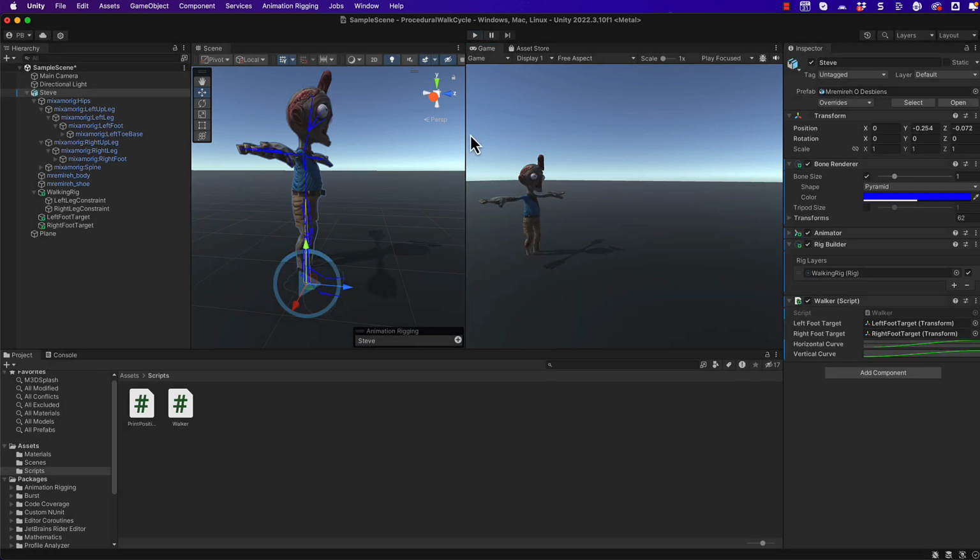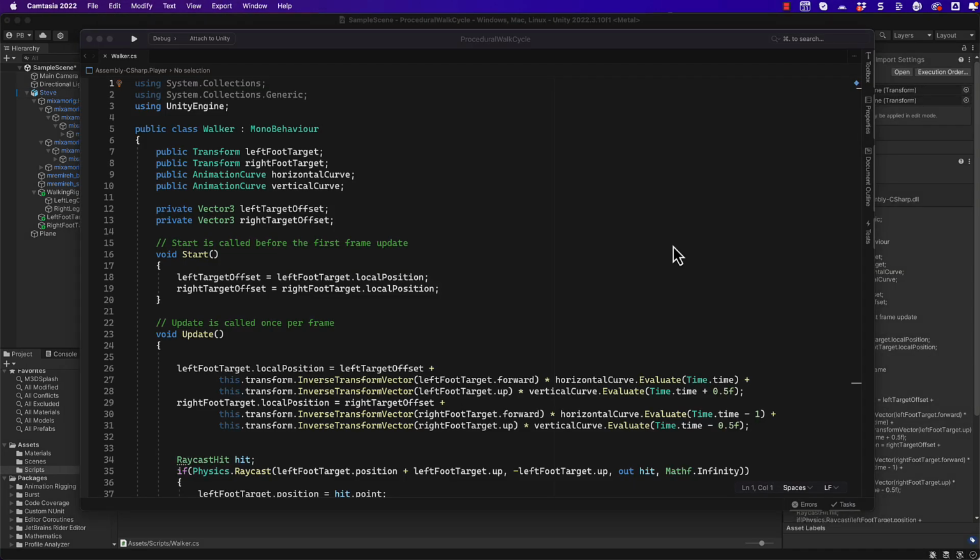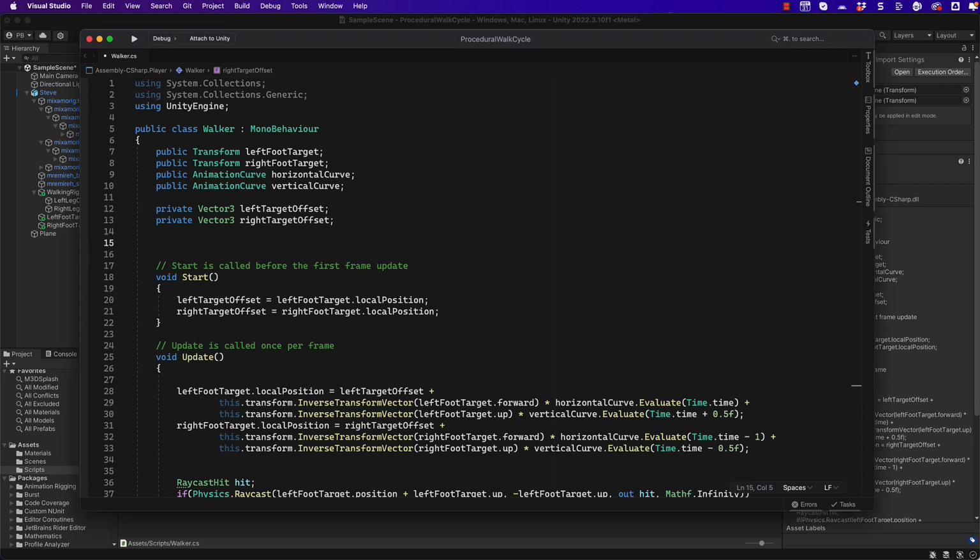Okay, right, great. Now, what we're going to do next is to put that vertical movement back in. This requires a little bit of re-engineering of the code. We need to figure out when either foot is moving in the backwards direction. If it's moving backwards, then we want to clamp our end effector to the ground. Otherwise, we want to let that knee lift the foot above the ground. So what I'm going to do up here is monitor the direction using the last position of the foot, which is the position of the foot in the last frame.